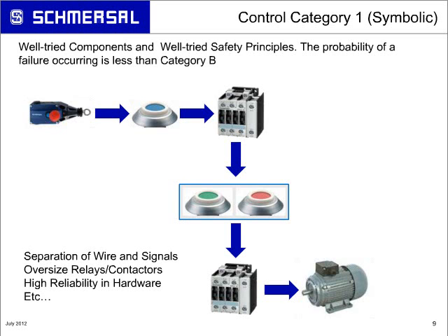current carrying capability. It doesn't mean that the contactor cannot weld or mechanically fail, but your chances or your likelihood of that occurring has been drastically reduced because you're not pitting the contacts nearly as hard or as often, so the contactor in a hardware reliability can tend to last a lot longer than one that's rated close to maximum load.